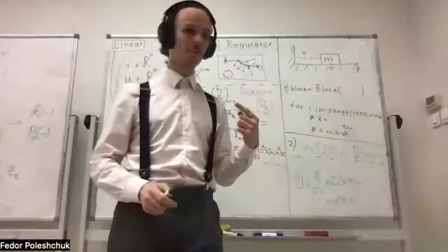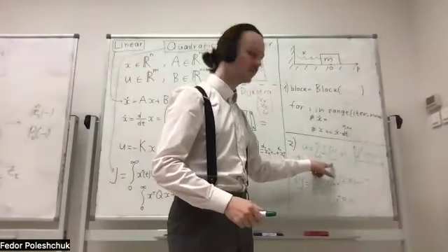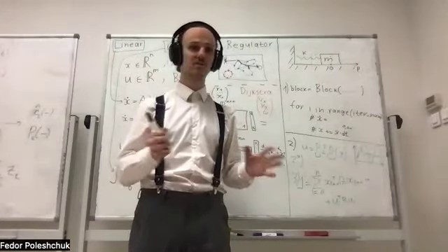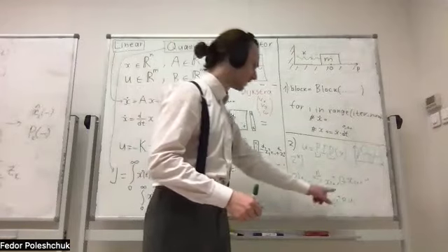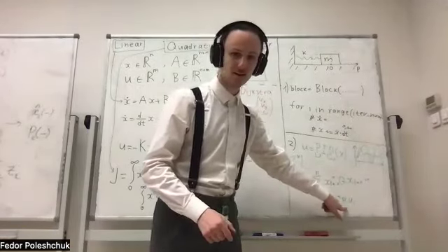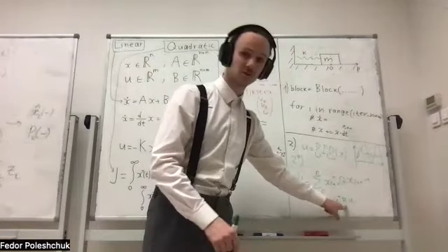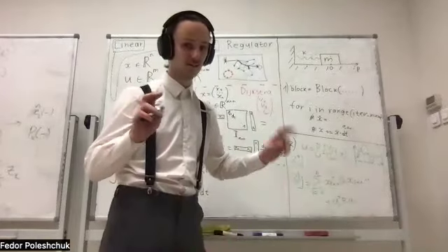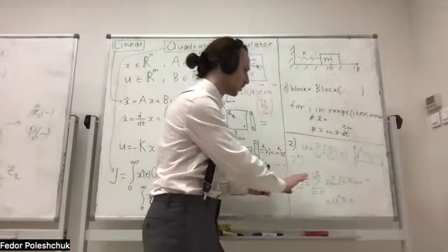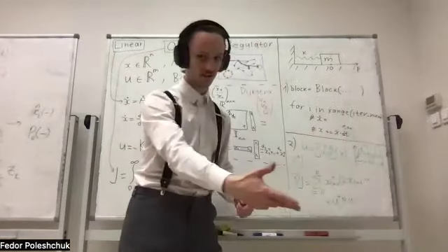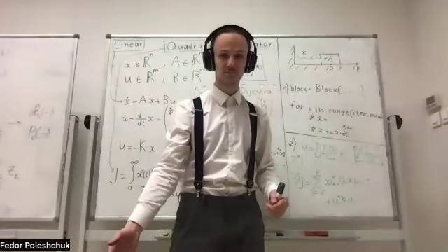Yeah. So you set a certain cost, and then you try to find P and D so that they minimize this cost. And you can try this for a couple of different costs, like a very big cost for deviation or a very big cost for control. If you have a very big cost for control, your controller should be lazy, and it's supposed to approach the desired position very slowly. So probably D will have to be big enough because we penalize velocity.